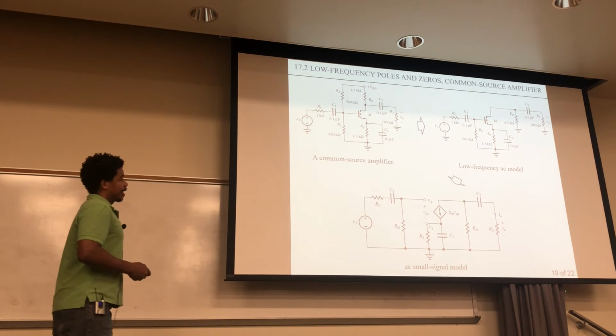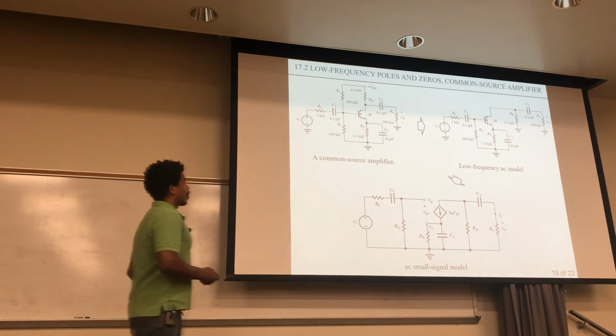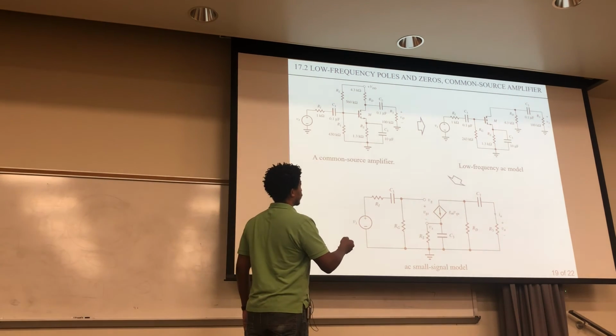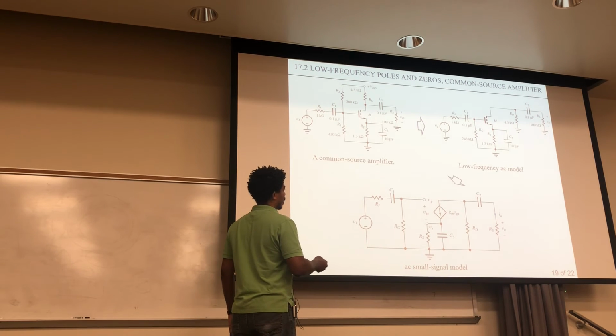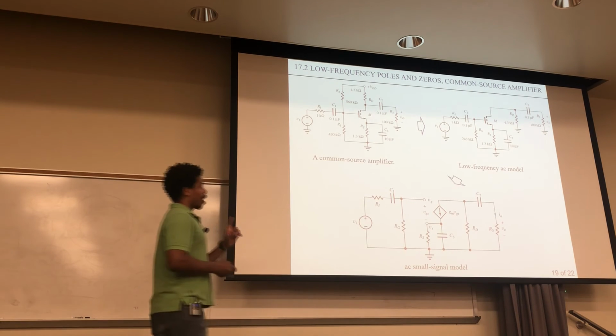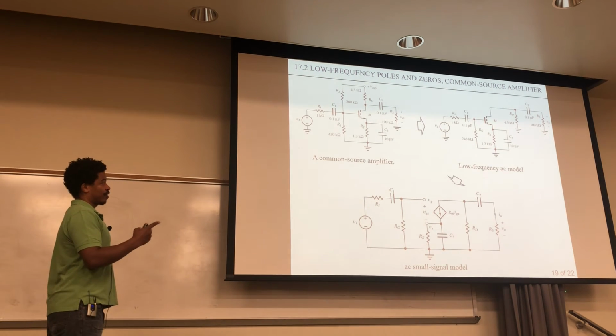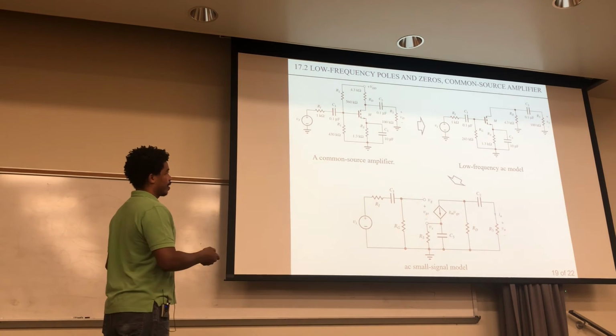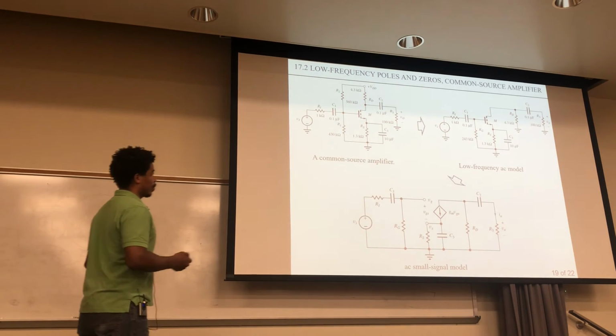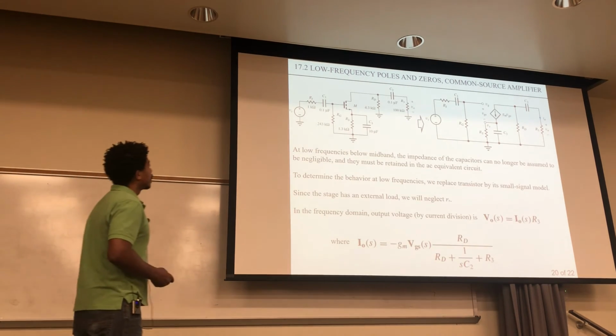Okay? And this is the small signal model where we take the FET right here and just replace it with this small signal model right here, because we're assuming that we're operating in the linear range and there's a very small variation in input signal, and that's linear. And so here's the linear relationship. So in dealing with this right here, we'll come up with our analysis.